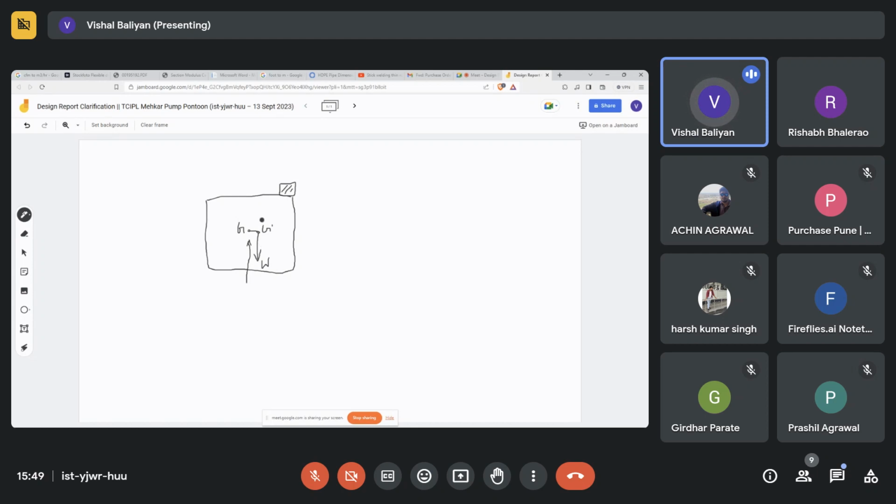center of buoyancy force to the line of action of gravity force, and that perpendicular distance is GZ, that is the righting lever. So if the ship is in upright condition and there is no list or heel, GZ is zero, so there is no righting moment. But even if we put a load which is off center and it is giving a heeling moment, it is again a part of the total weight.